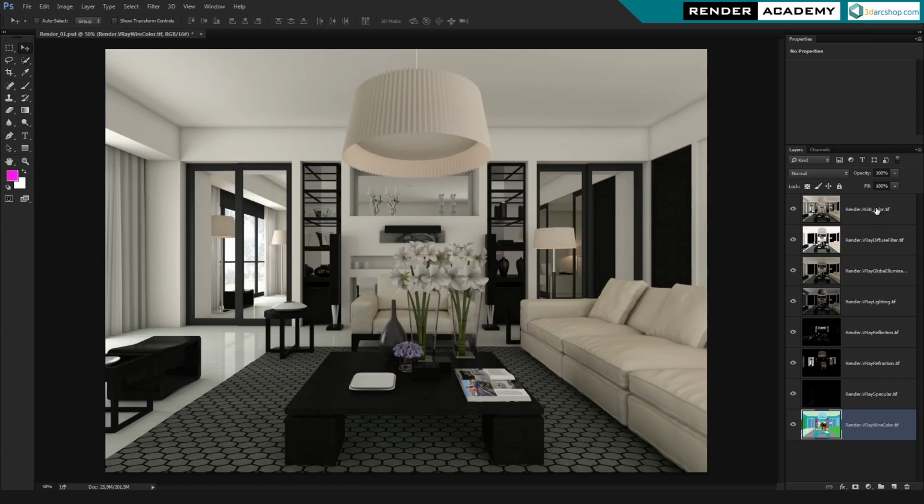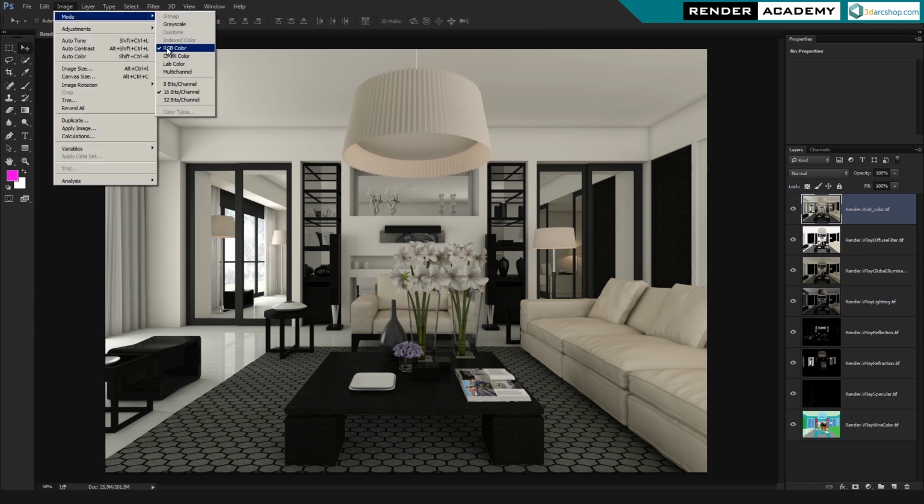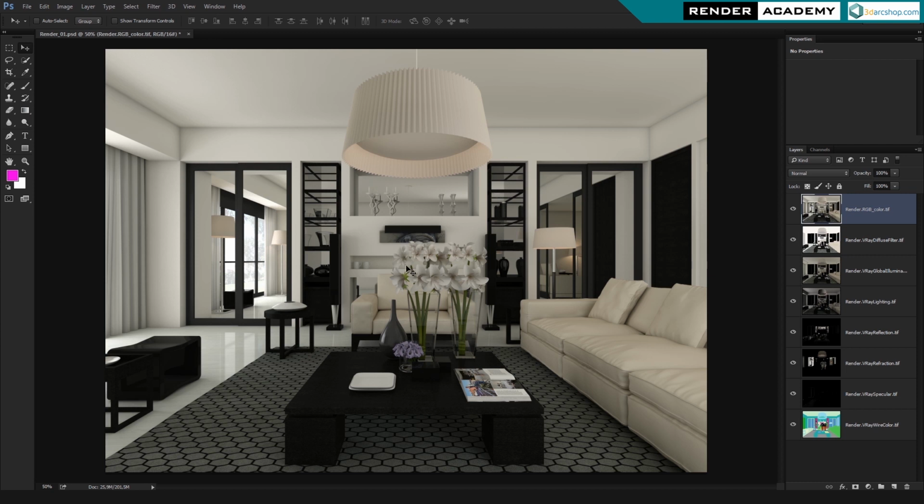This is because V-Ray doesn't know what I'm using. All the files have been saved in TIFF file format, and I'm working in RGB, red, green, blue. So my image mode is RGB, and I have 16-bit per channel. Somebody is using the linear mode, 32-bit per channel. I'm quite comfortable with 16 because 32 is good for the exposure and the HDR or EXR post-production, but with 16, I told you, I'm comfortable and I can obtain a good result without having such a heavy, linear corrected, gamma corrected picture. So I'm quite satisfied in this way.